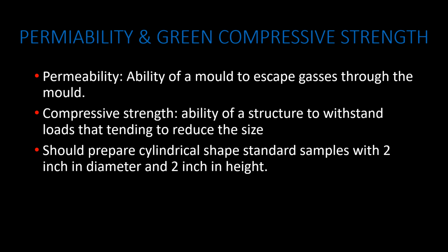Permeability and compressive strength. Permeability gives an idea about how well sand can vent. If the permeability is higher, there should be a more open structure in rammed sand. It leads to rough casting. If particles are tightly packed, it means permeability is low. That leads to pinholes. Compressive strength is the ability of a structure to withstand loads that tend to reduce its size.